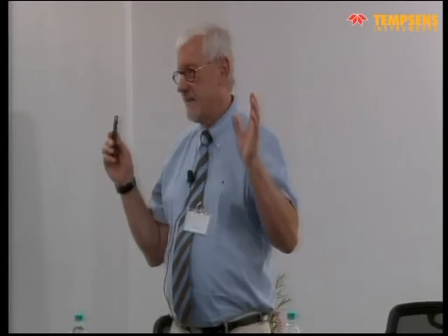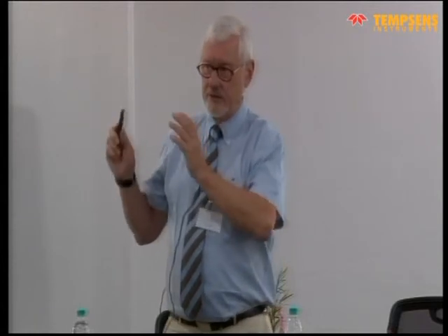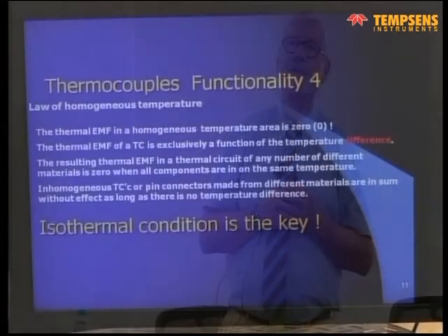And again, what you measure is only the temperature difference between your reference junction or your cold junction and the hot tip. Nothing else. You need to know the cold temperature as well to know the actual temperature.